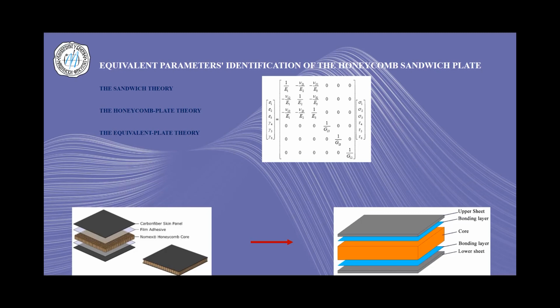And of course, this is all done in order to recognize the elastic coefficients that we need in the generalized Hooke's law. For this kind of structure, there are quite a few of these elastic coefficients that we really need to know in order to relate strains to stresses, which is what we do in other kinds of industry too. But as I say, this approach is valid, I would say, for a static analysis.